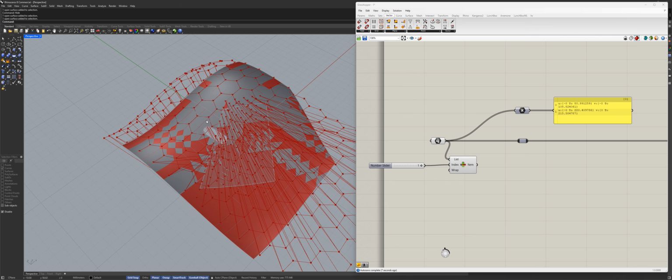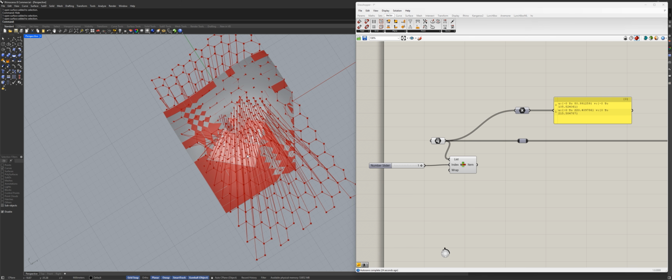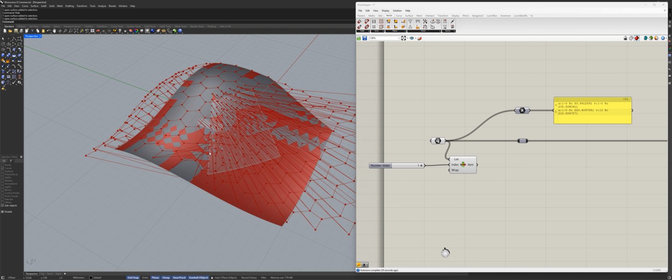Why? Well, because every single surface is unique. Every single surface has very specific geometric properties, its own basis functions, its own parametric domains, and its own orientation. They are indeed different, and the fact that they are joined together continuously doesn't mean that this is one object with a uniform domain. It is not. There are two, or maybe three, or maybe five, or maybe 50, or maybe more than 100, which is quite a common scenario when it comes to modeling. Because when you model, you construct your surfaces with multiple different surfaces, right? Different patches, different angles, different trims, and so on and so forth, and they are all unique.